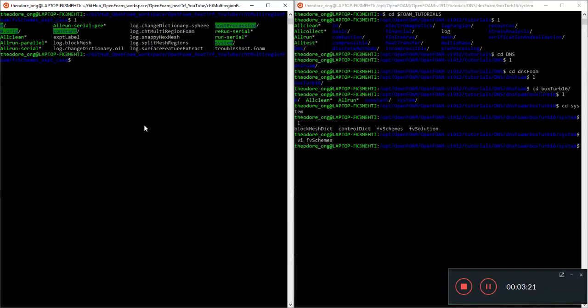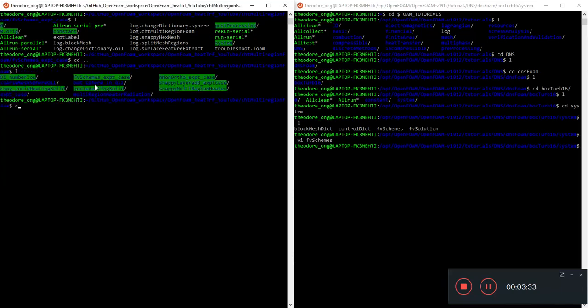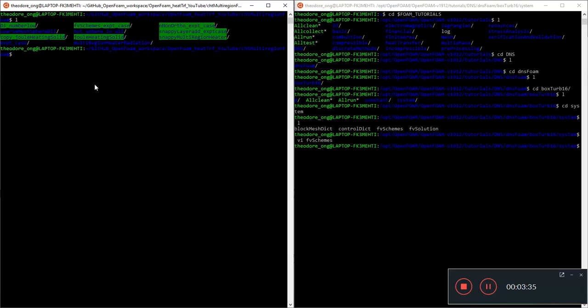We can guess that the problem is the mesh, because there are no layers added and it's really small and oddly shaped, so the mesh quality may be a little bit poor. That's the reason why we want to try refining the mesh using snappyHexMesh and the layer addition.